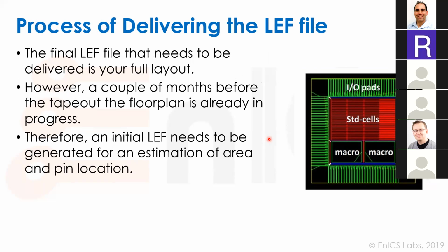But Slava can't wait until we finish everything. So a couple months before the tape out itself, there's already a floor plan process. So we need to generate an initial LEF, just for an estimation of the area, usually according to what the SOC tell us, what kind of estimation we need, if we can be correct within 50%, 70%, just to know the approximate size of our block. And the pins, hopefully we already know what pins we need, how many pins, and also their placements.